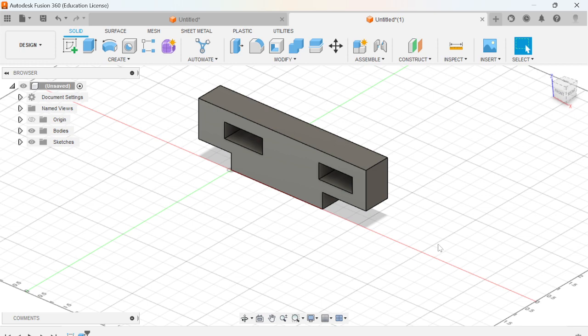Another good thing that I was taught by a mentor in high school is you always want to design with the end in mind. For these beginning projects, that's not going to be as important as we're making basic shapes, but when you start your final project, you should already know everything about your design before you start designing, because if you get to the end and realize you made a mistake, if you made everything dependent, meaning every feature is dependent on the last, and you made a mistake on your first feature, you go in, you change that feature, your whole sketch breaks, your whole model breaks.